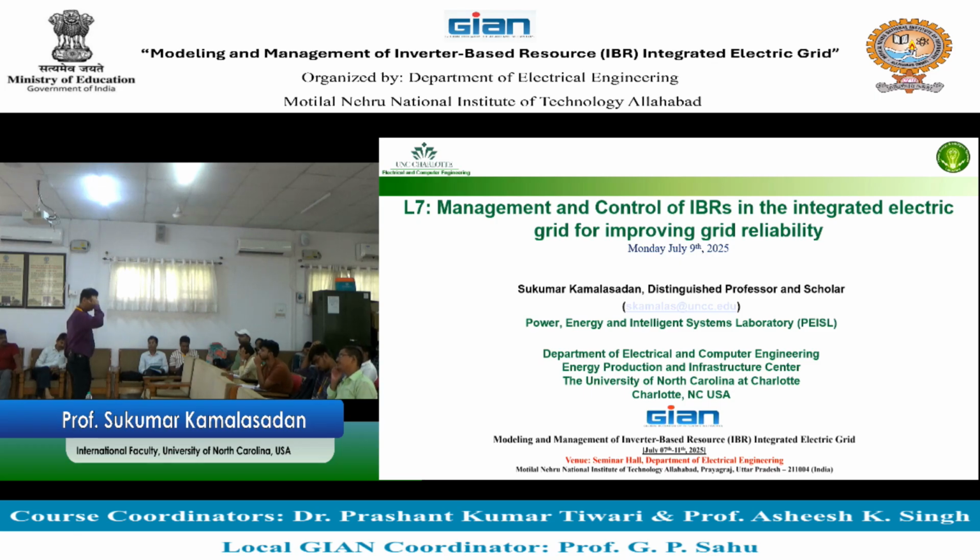Talk about the storage. This is dispatchable. Here, if I want 5 megawatt, this guy cannot give 5 megawatt, because there is no sunlight. So how do you make that inverter or the PV farm dispatchable? The only way you can make it dispatchable is by energy storage. That's the only way you make the PV farm dispatchable, right?